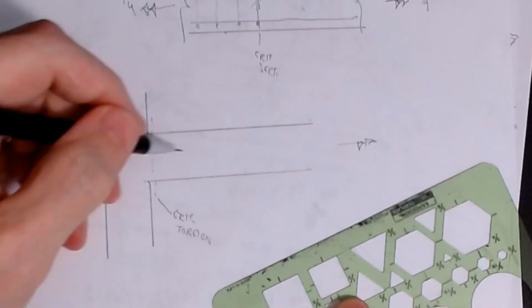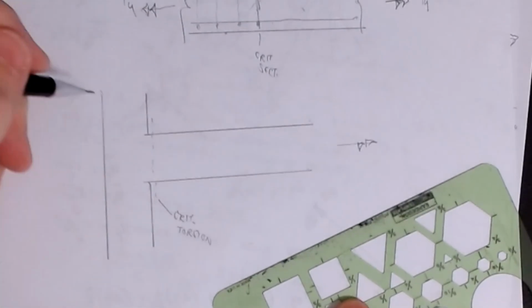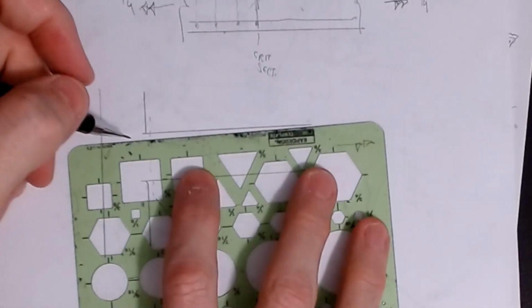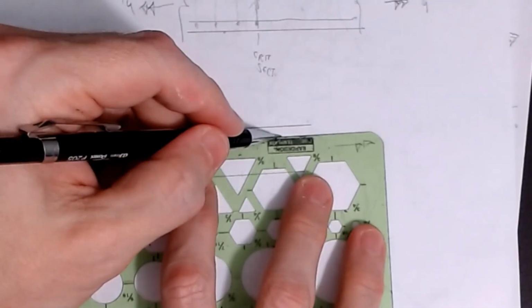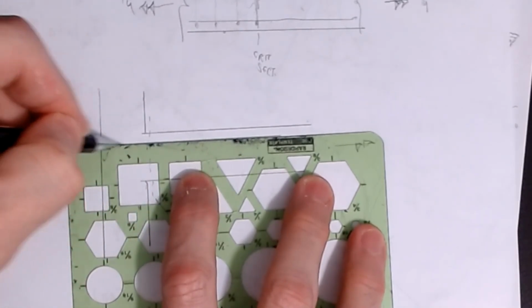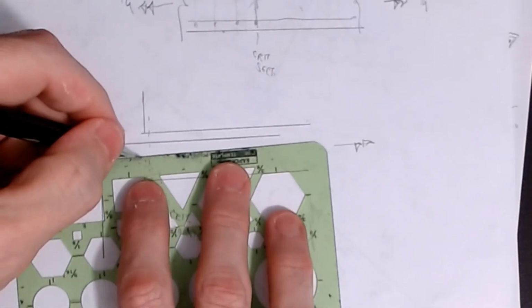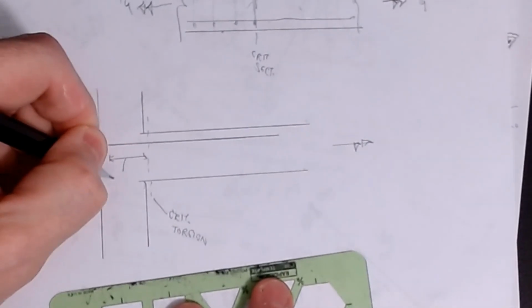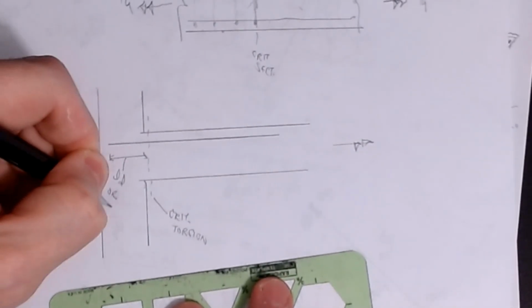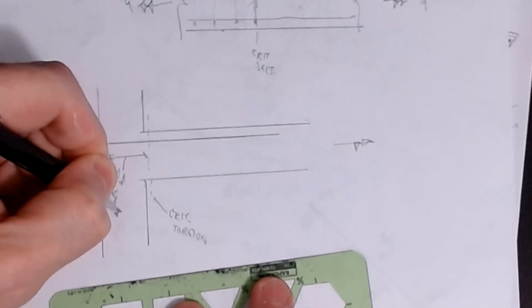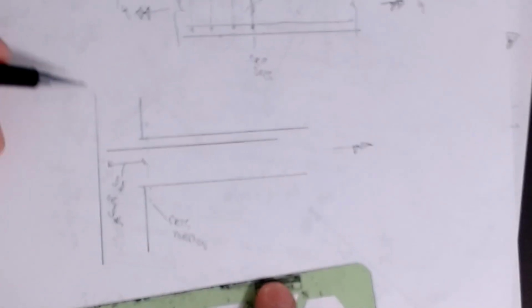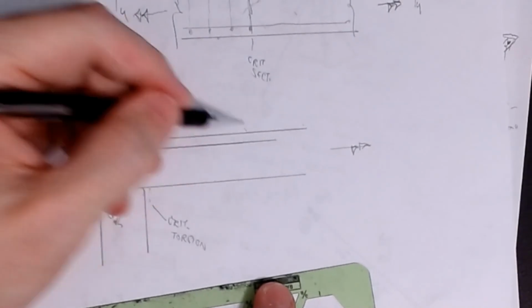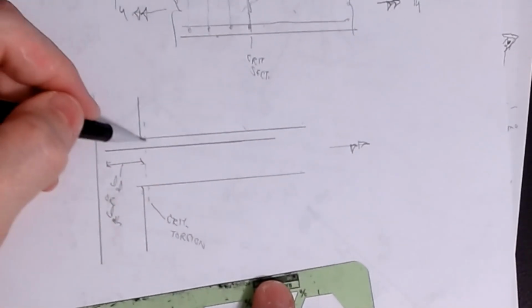It's not plus d like we do with shear, it's at the face. Which means that if I'm trying to anchor a negative bar up in the top, I have to provide either ld or ldh, depending on if you put a hook or not, to get those bars anchored in, starting at the face. It's no longer at the critical section or out in the middle somewhere, it's here.